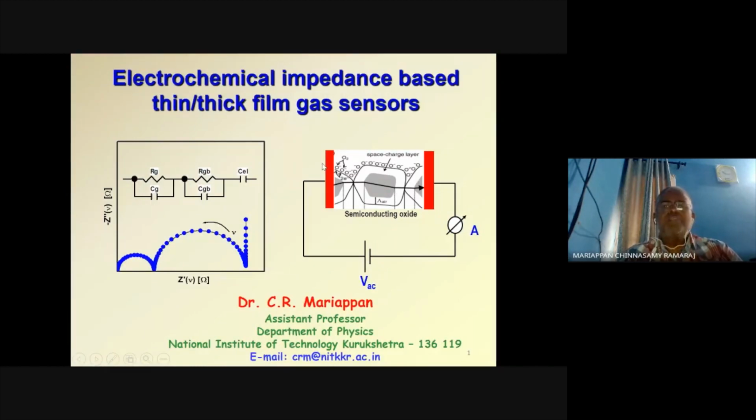If you look at the properties of these materials, what is happening inside, what changes are happening inside. In the case of a light dependent resistance sensor, there is a change in the resistance depending upon the light intensity. If you look at the mechanism behind this, light is nothing but photon energy. This photon energy is falling on this material, so there is a sudden change in the resistance. That means the number of charge carriers is changing.